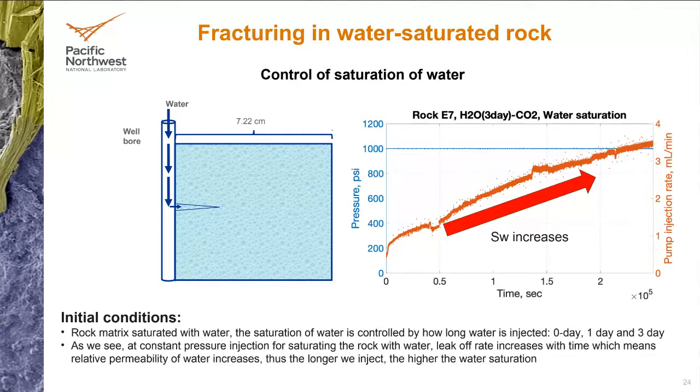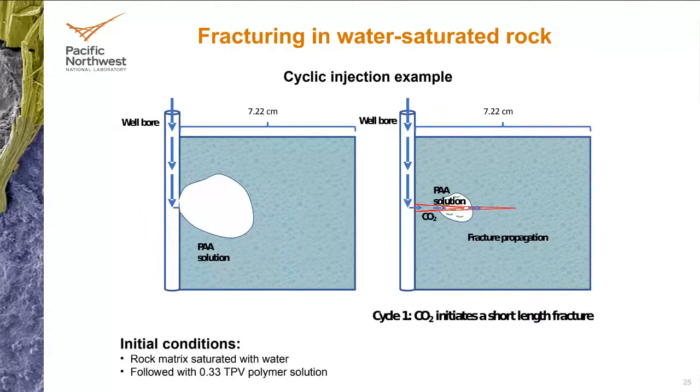Okay, so that I think is shown in this next slide. So we let it at 1,100, 1,200 psi. The polymer solution will get a little bit diluted because it's a water saturated rock, but you have probably some distribution like this across the entire sample. And then we introduce CO2. We stop that pump, we close the valve, and we swap to the CO2 pump, and we introduce CO2 at constant flow rate until the fracture occurs.